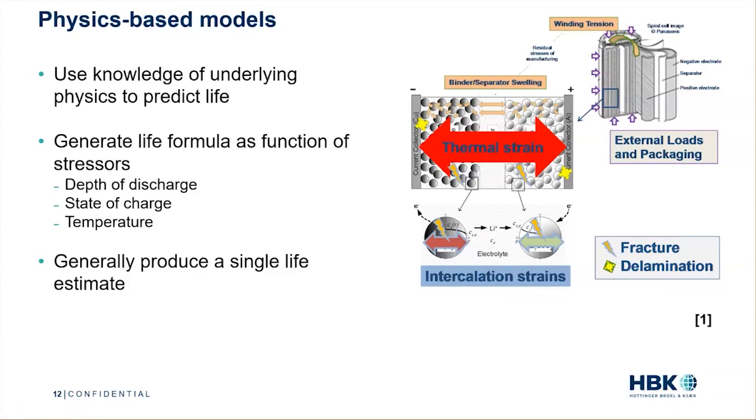Well, what does that really mean, right? If we know that our target life is 8 years and our formula tells us it's 12.7 years, does that mean that we have 0 failures? Not really, right? And furthermore, let's say we've got 2 failure modes, one characterized by one equation and one characterized by another equation. And we say one of them has a life of 12.7 years against failure mode A, and another one has a life of 9.9 years against failure mode B. What does that mean for the whole battery, right?